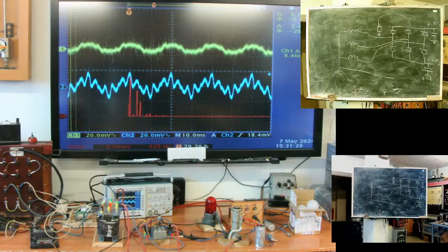Number one, what kind of customers do we have? There are those customers that just need three-phase, but a customer can have three-phase load and single-phase load. For small customers, like small homes, we need a neutral line because you should always predict the case when one switches on, for example, a water heater, and on the other side is only a small TV.